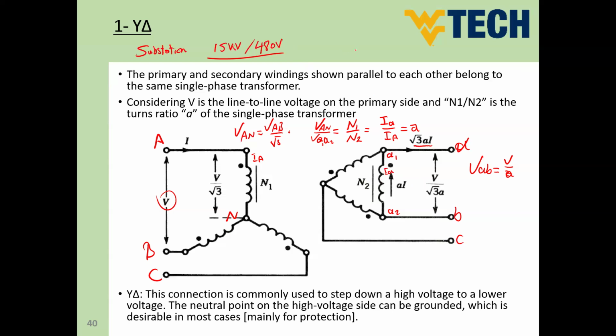So by experience, guys, we can say that 80% of substation transformers are delta Y, because 80% of our substations are desired to supply domestic loads. So this number is actually from a transformer company. So they say that they can sell like 80% of their product as delta Y connection for substations. So this is what we have in industry.